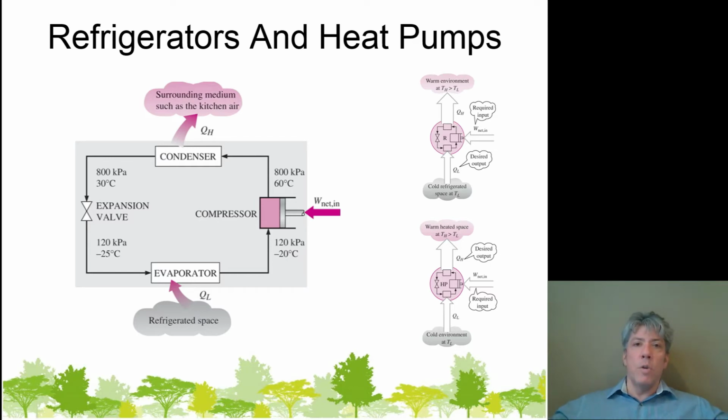The atmosphere is a huge thermal energy reservoir, so it's pulling thermal energy from the thermal energy reservoir, but that's not why you buy the heat pump. You buy the heat pump to then take that thermal energy, raise it up to a higher quality or a higher temperature, and then put it into your home.